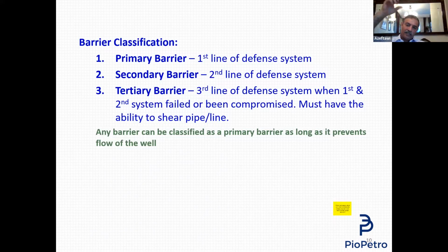During running in the hole, there is friction between this pipe, this steel element, and the rubber. This friction causes the rubber to wear. So there will be a gap between the rubber, and if this happens, what we normally do is increase the pressure on this rubber element that seals around the pipe or around the wire to prevent the flow of the hydrocarbon.